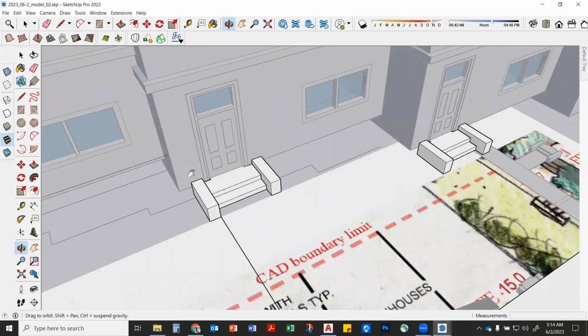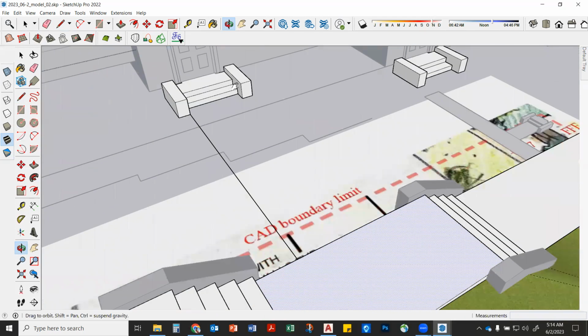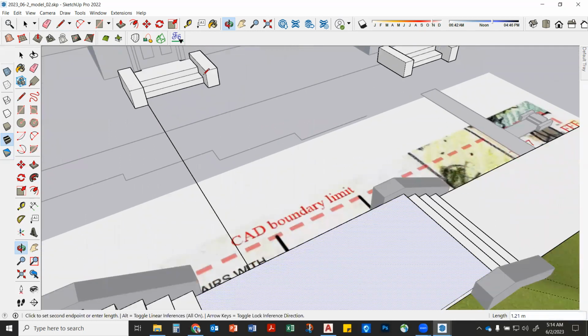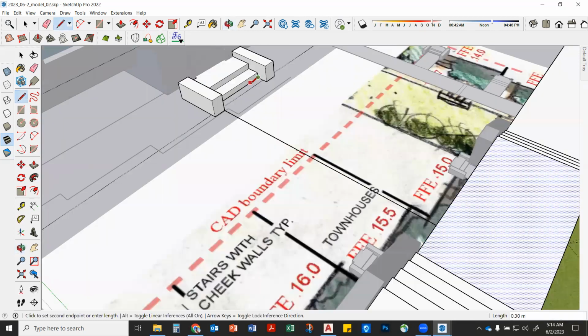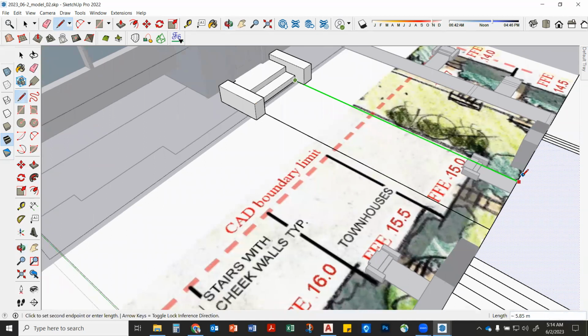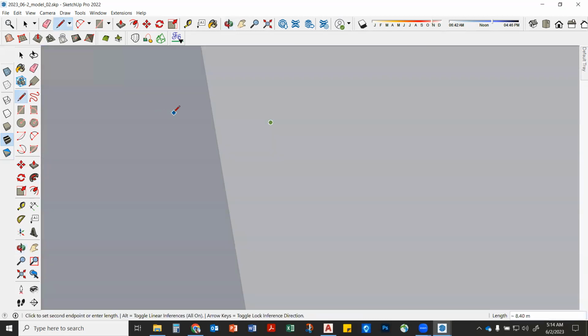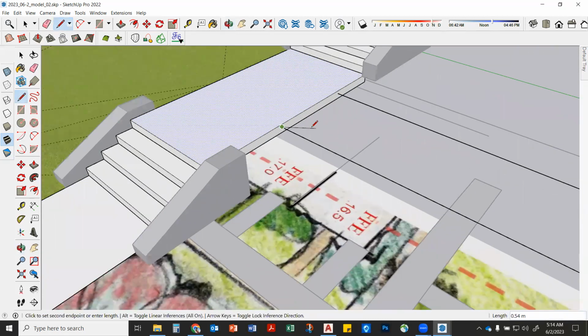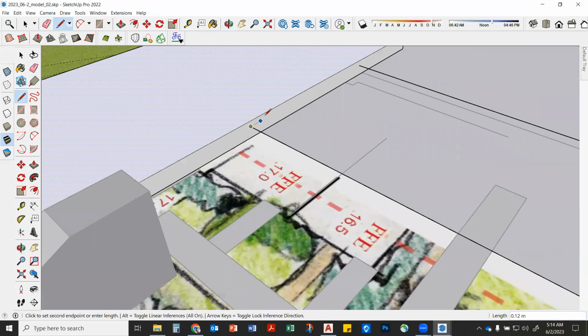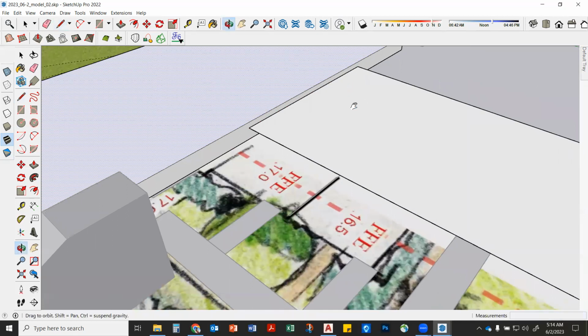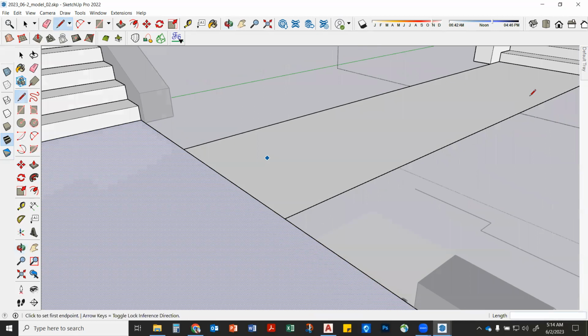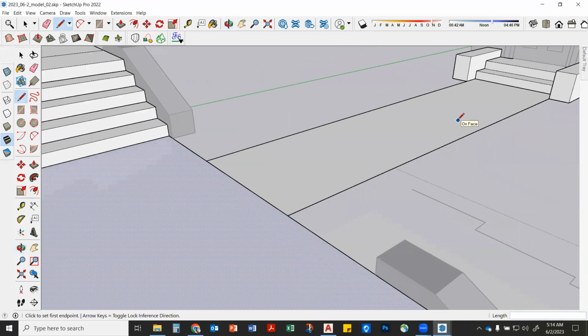All right? So moving around in SketchUp is really key. And the better you get, of course, the faster you can do it. Anyway, so I'm rotating it around. I'm going to lock it on the green axis again. And then I'm going to come over and have it click right there, okay? And then look, then if I wanted to just make that face, I could go from that endpoint to there and I have a face, yeah? Make sense?